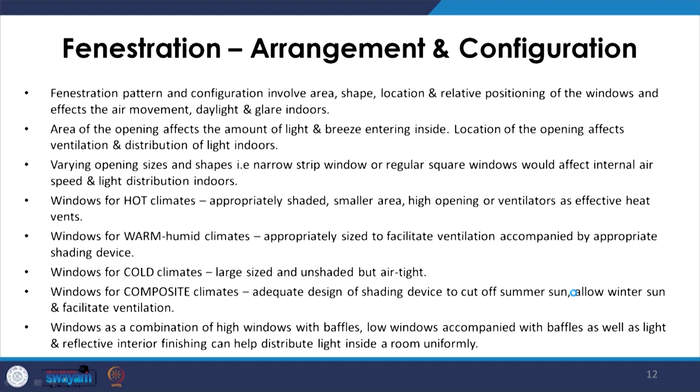Next, we talk about the arrangement and configuration of fenestration. Now, fenestration in today's times becomes one of the most important elements of building, because it affects the movement of air and hence the temperature indoors. It allows for light.